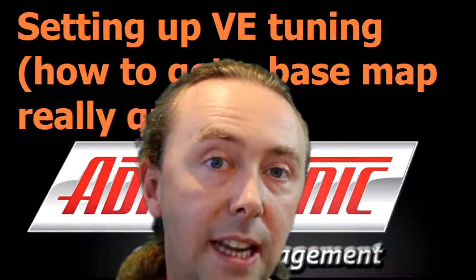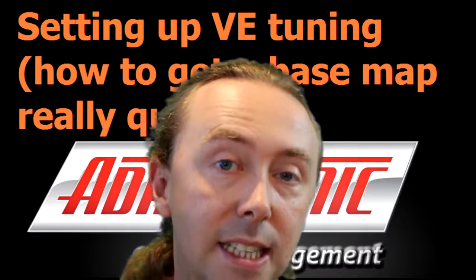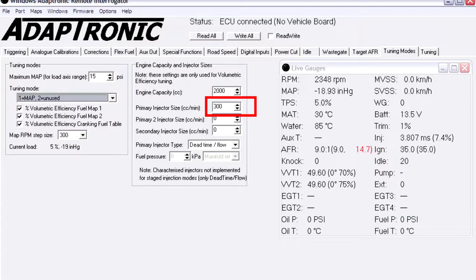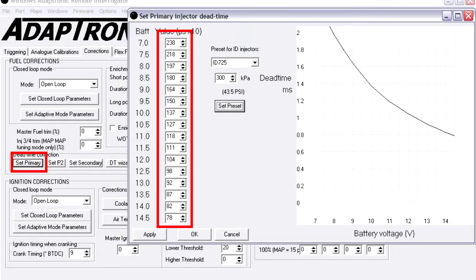0. If you're using any other sort of injector, then enter the injector flow rate in cc's per minute in the primary injector setting, and again make sure the primary 2 and the secondary size are set to 0, and then go to the primary injector dead time setting and enter the dead times as a function of the battery voltage at the fuel pressure that you're running them. Note that a value of 1 in here corresponds to 10 microseconds, so if the dead time is 1 millisecond, then you'd enter a value of 100.